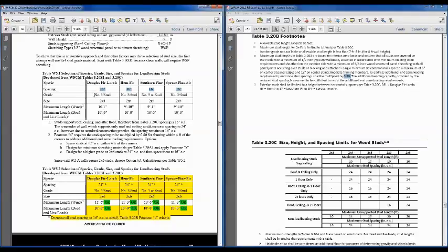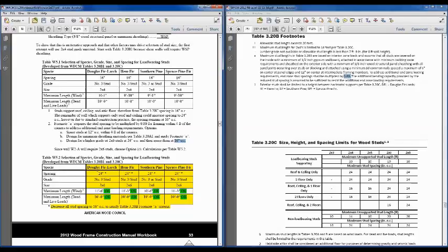We could use number 3 and stud 2x4s, and then at the corners space those at 12 inches on center because of that adjustment. Or we could design for a higher grade 2x6 stud at 24 inches on center, and then because of that adjustment factor back off to 16 inches on center. And so that's what we're using as a solution here.